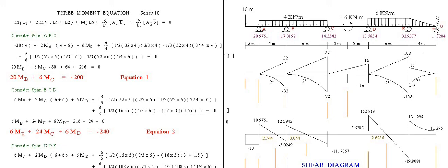The reaction at F is 1/3 of 12, and the reaction at E is 2/3 of 12. 1/3 of 12 is 4, the reaction at F. Then multiply that by 4 to make a moment. It is 16. Then right away, this is also 16, because these two must be 0.